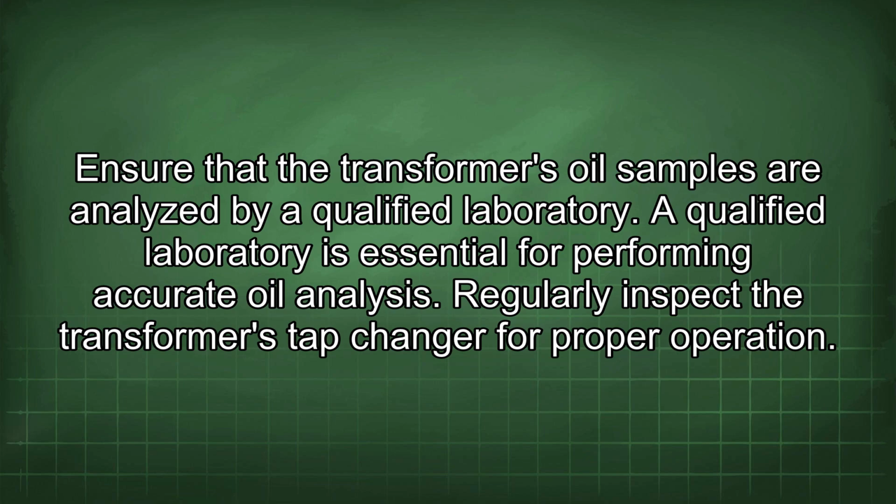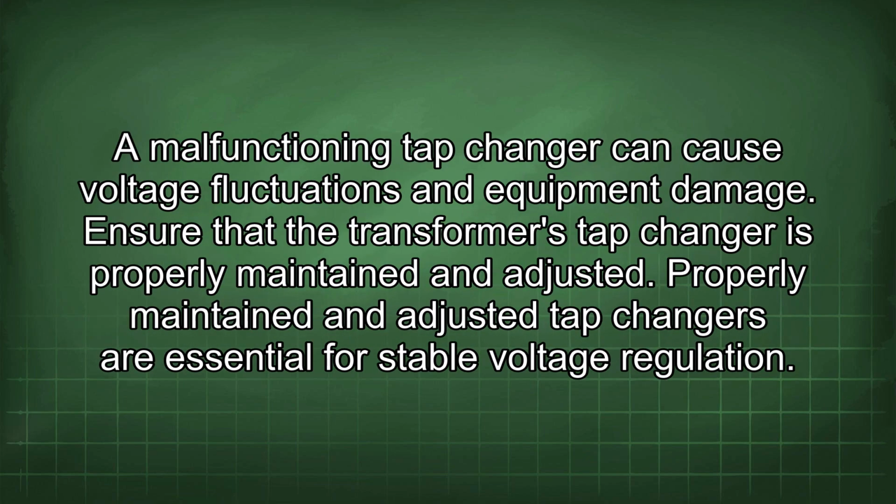Regularly inspect the transformer's tap changer for proper operation. A malfunctioning tap changer can cause voltage fluctuations and equipment damage. Ensure that the transformer's tap changer is properly maintained and adjusted. Properly maintained and adjusted tap changers are essential for stable voltage regulation.